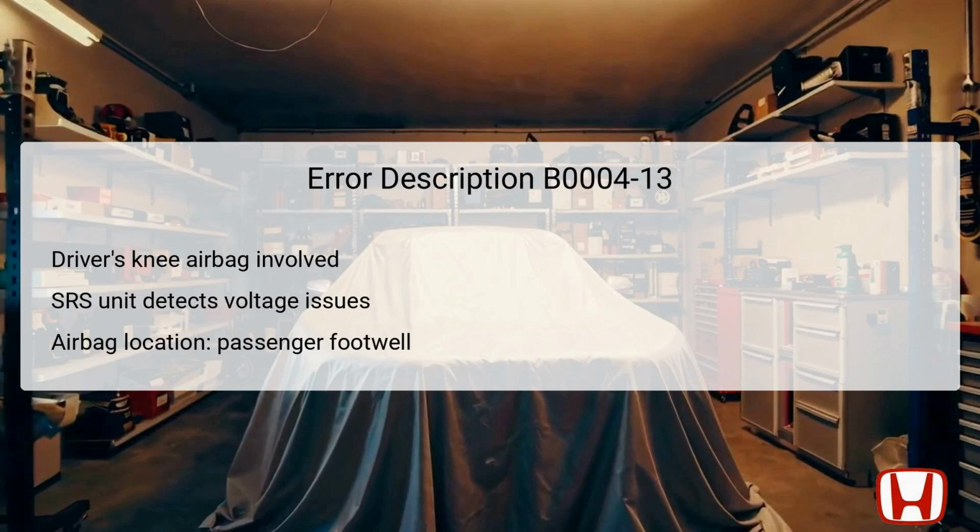The SRS unit, which serves as the central control for the airbag systems, continuously monitors voltage levels. If it detects that the voltage on the detection line exceeds a certain threshold, it interprets it as a fault and subsequently logs the DTC B0004-13 in its memory. Such an increase in voltage can imply an open circuit or increased resistance that disrupts normal functionality. Included in this diagnostic procedure is an inspection of the airbag, the wiring leading to it, and the SRS unit itself. Understanding the role of each component is crucial to effectively diagnosing the issue.